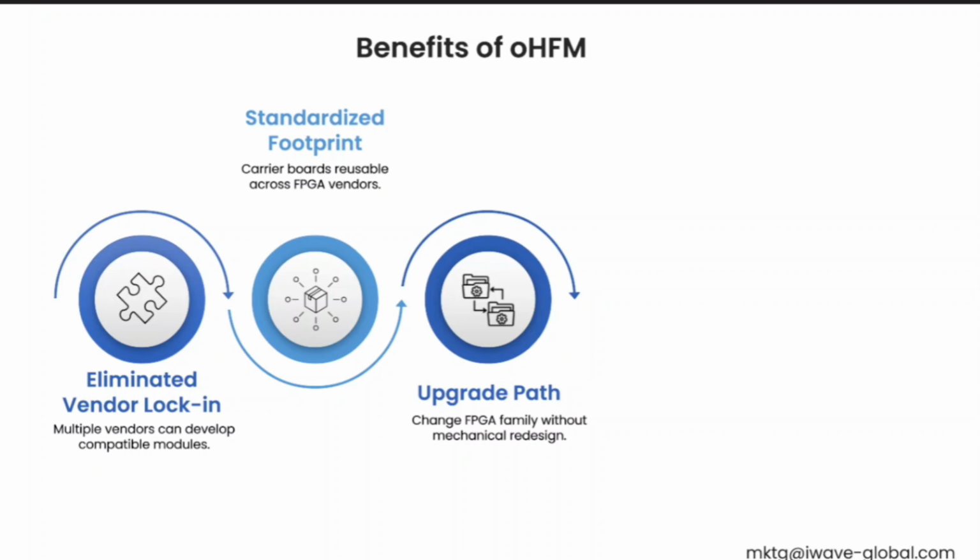If you have designed your carrier card well, you can use the same carrier for the lower-end size S and also size XL. Based on market demand, you just change the module and, using the existing enclosure, have multiple price points and multiple configurations of a single system with very limited modification.